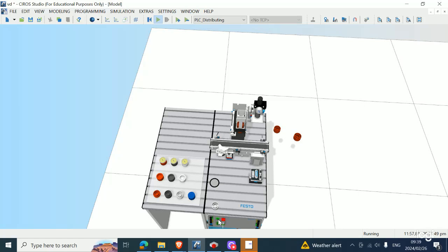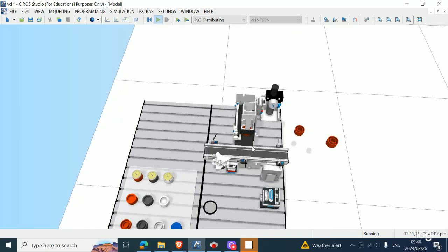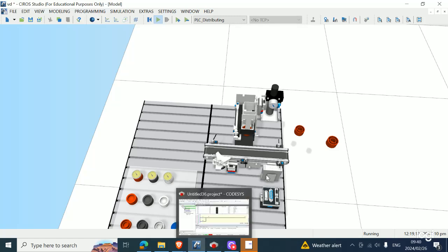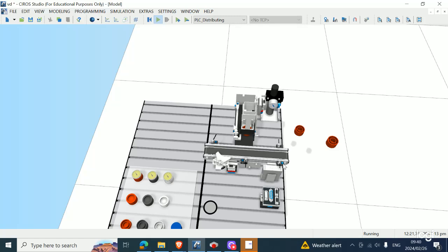So now I insert a part, and then the sensor detects it and moves it to the end part of your conveyor. But as you can see, with how this circuit is working now, the parts are falling off. So if you want to ensure that when the parts reach the end of the conveyor they stop, you can use this sensor to stop the parts. If we look at the state of this sensor, it's normally closed. And then when the parts move past this sensor, it turns off, right? So I can use this sensor to stop the conveyor belt in this regard.